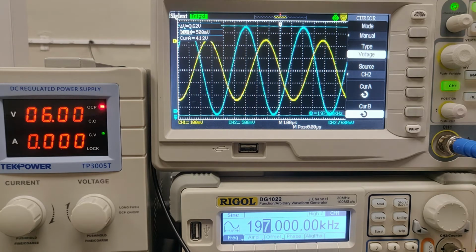So if you look at equation 1, it's an equation that gives our V out as equal to this A sub O, which is the open circuit gain, or open loop gain, I guess, which is a very large number. And all of these circuits that we're building are closed loop setups, but this is kind of a universal equation.